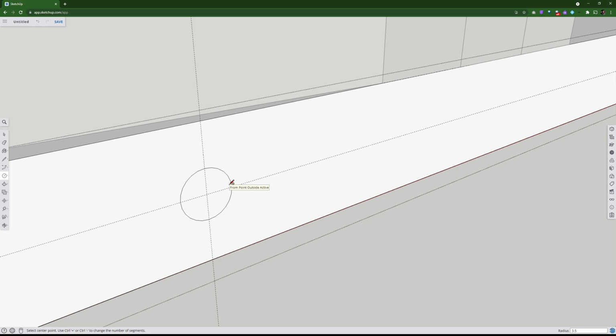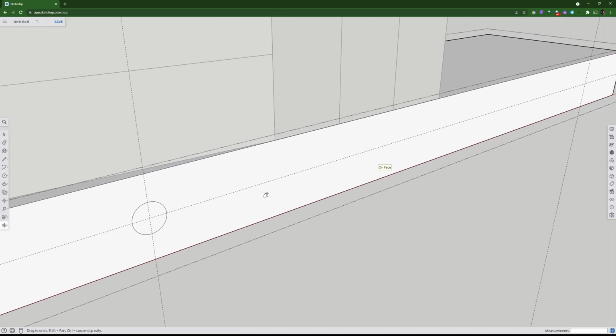There it is. I'm actually going to do a little trick now. I know that SketchUp draws a 24-sided object. I'm going to make mine a bit smoother, a bit rounder. I might double that and type this in. Okay, so as soon as I've done that circle, I'm going to type in 48S. And make it a bit smoother. Okay, so 48 sides.